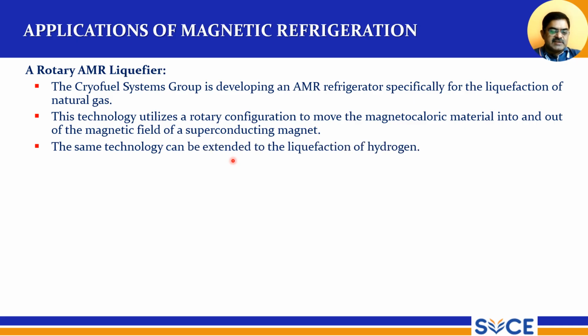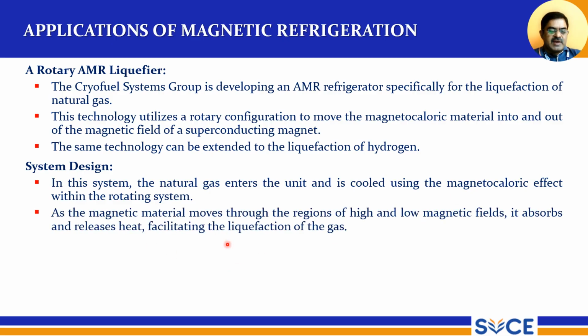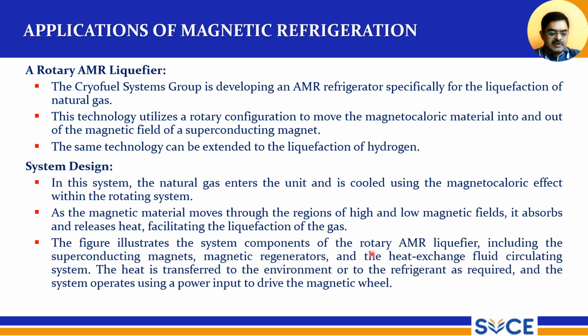The same technology can be extended to liquefaction of hydrogen. In this system, the natural gas enters the unit and is cooled using the magnetocaloric effect within the rotating system. As the magnetic material moves through the regions of high and low magnetic fields, it absorbs and releases heat, facilitating the liquefaction of the gas.